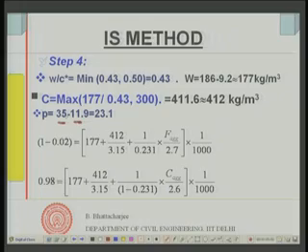I had earlier 35, if you remember, I had 35 minus 11.9, and this 11.9 comes because 7% I can reduce because of the rounded aggregate, and I reduce 1.5% because of the zone of the sand, which is zone 3, and also I reduce 3.4% because of the change in the water cement ratio. So, considering all that, the total adjustment is minus 11.9 from 35, and that gives me 23.1%. So, my P is 23.1%.